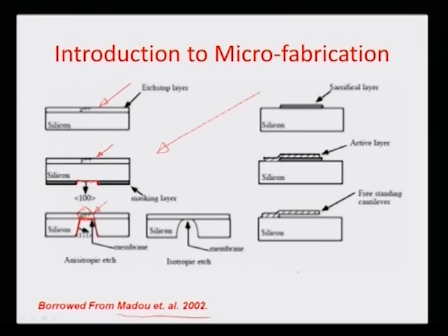On the other hand, this side is showing how a micro cantilever can be generated by additive micro machining, where you have, let us say, a sacrificial layer over which you have put a polysilicon layer like this, and then you are removing the sacrificial layer away, so that you can have a small cantilever which you have illustrated here in this particular example. So, these are some of the process flow charts or logic diagrams for formulating some of these micro features and micro structures in different illustrations.